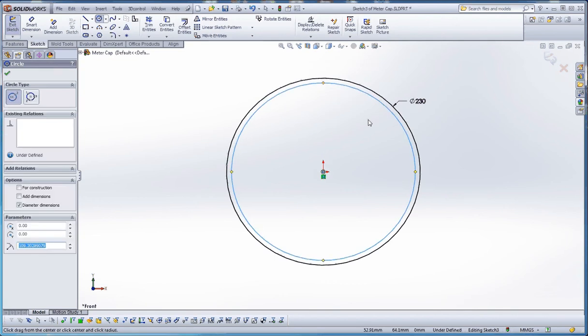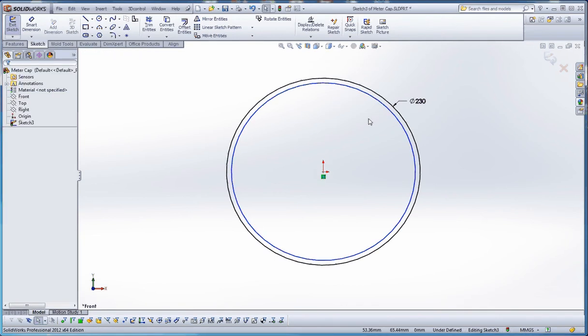And what we're going to do with this circle, if you remember what SolidWorks does, with the solid line, with a basic sketch line, it's going to do something 3D with that. But if you were to turn this circle into reference geometry, such as a center line or a construction line as they used to call it, it won't regard that. But we can still use it as geometry in our model.